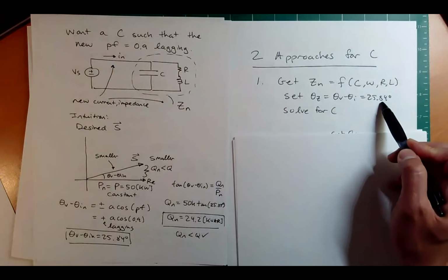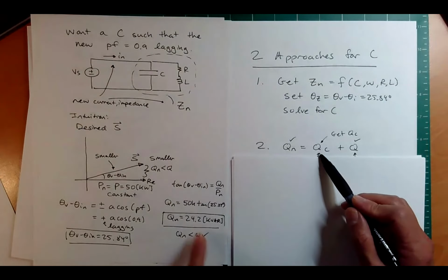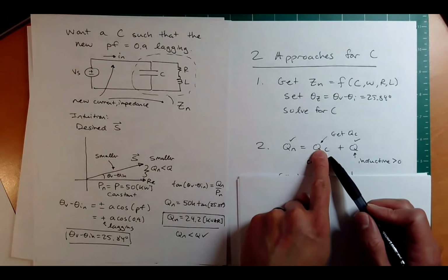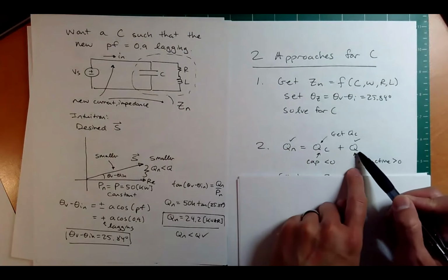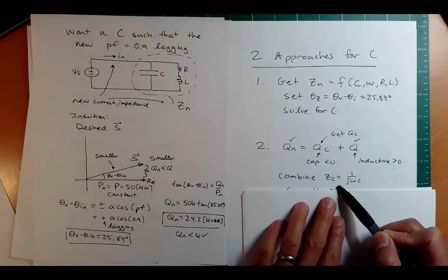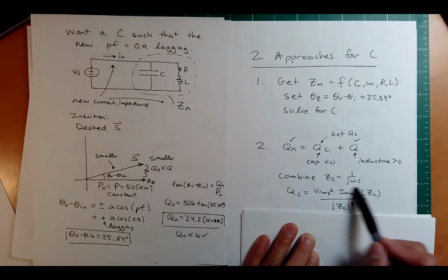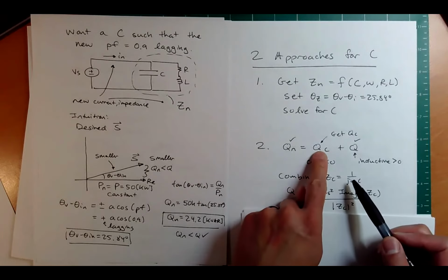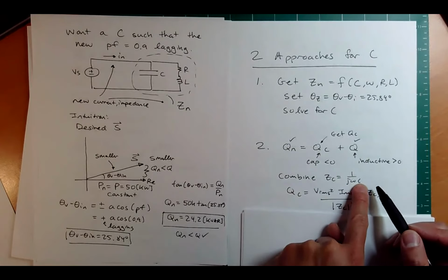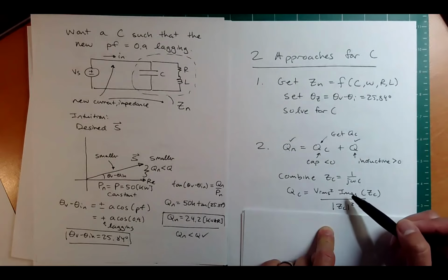Another way I can do it is to look at it from the power perspective. I can say that my new Q is 24.2. I don't know what QC is, but I know it has to be the difference of the new Q and the original Q, which was 66. So that's easy to solve for. Then I know that the impedance of the capacitor is just 1 over j omega C, and I know this reactive power formula. So if I know what QC is from the subtraction of these two, I have this number. And then look at that: I know omega, I know V, and I can punch that in, and again I would get one equation and one unknown.